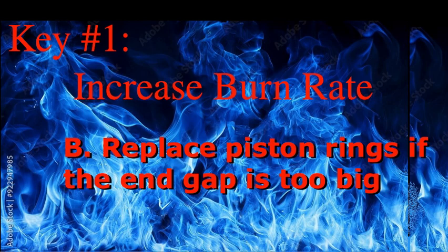Increasing compression increases power. Unfortunately, it also increases engine heat, which is why I would also recommend lathing the mating surface of the head down to increase the compression ratio. But usually engines come with a good average compression ratio that works well for the engine.